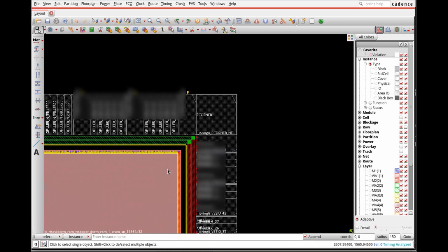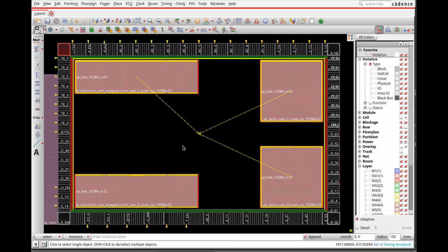The second thing is we have the follow pins, which are the standard cell rows. So I'm going to have rows in metal 1 all over here, and the rows can easily connect on these 2 sides to the rings, the VDD and ground rings. And when the rows are over here, they can easily connect to the rings that are around the macros over here. So these rings make easy connections and so forth.